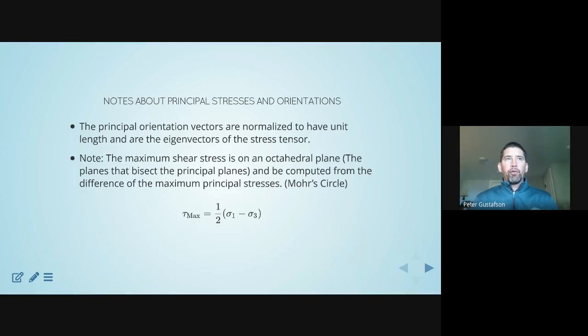Now this, of course, is also going to be an important mechanical concept, the maximum shear stress, because this very much relates to yield in ductile materials. The maximum normal stress is really critical for brittle materials because that has to do with crack propagation. It turns out the maximum normal stress also is critical to materials that yield, i.e. ductile materials, except it's a little bit backhanded, meaning that you first need to calculate the shears. But we'll spend a little bit more time on that later.